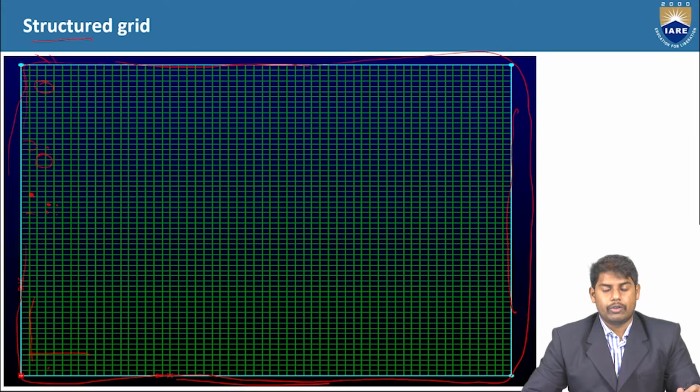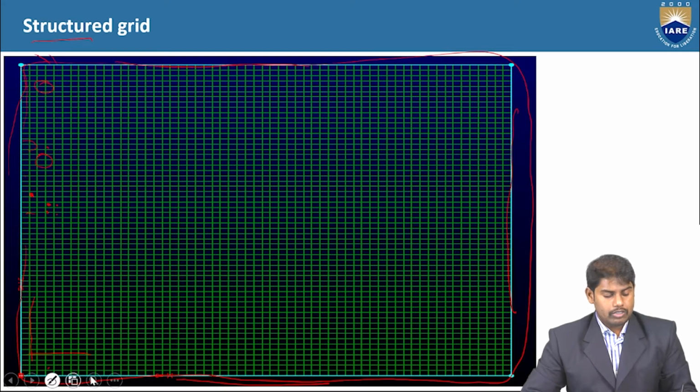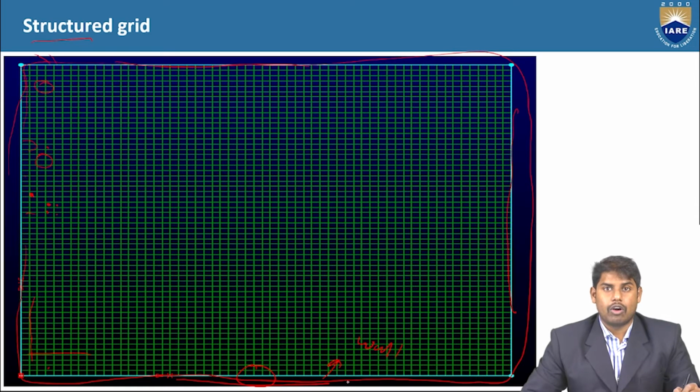For that case we need to give realistic boundary conditions to simulate the real flow phenomena. Here on the bottom surface you have an entity called a wall, so we have to give this condition as a wall condition.